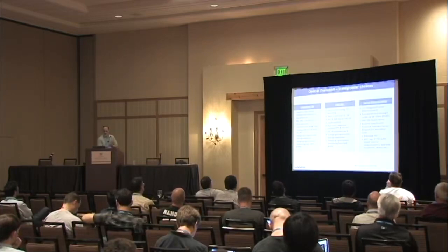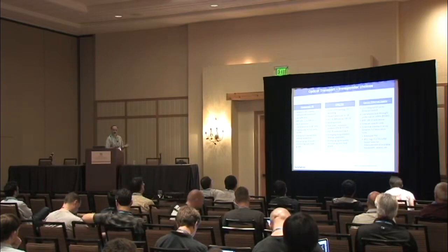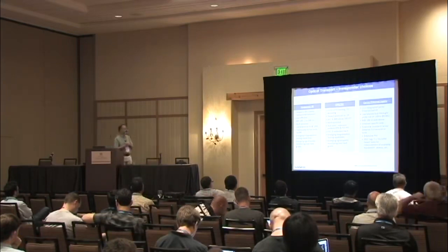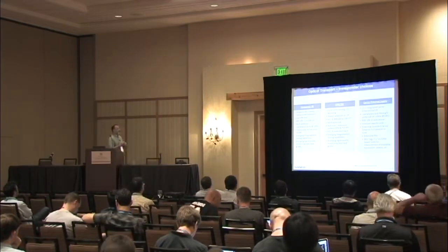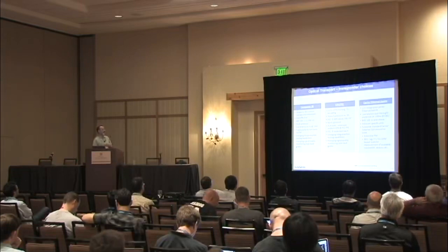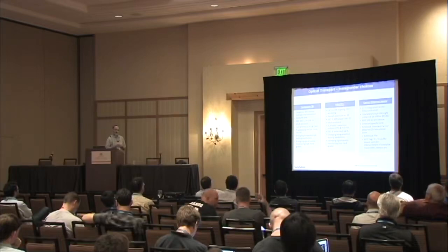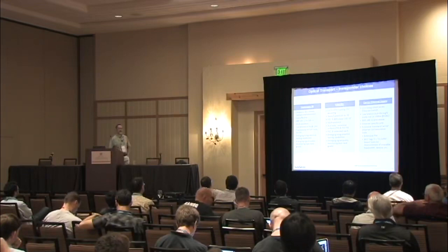Looking at transponder choices, and that's external transponders, not inside the switches. The simple transparent 3R, layer 1, retime, reshape, and retransmit. This is the most cost-effective option. Bit error rate within the standard industry ranges of 10^-12, 10^-14.